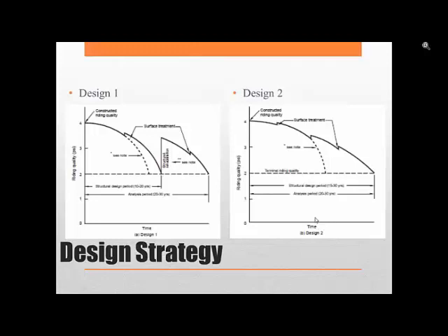Design 2, which is structurally adequate for the whole of the analysis period, note analysis and structural are similar, requires only 3 resealings, 1, 2, 3. Resealings are typically done between 5 and 7 year spans. This is typical of lower order class roads like a D and a low order C.